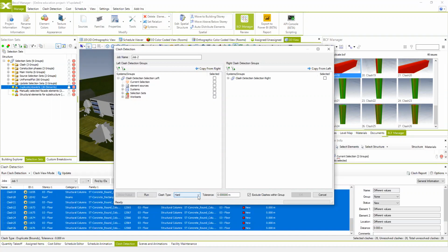Otherwise, if you want to check your BIM model elements just for some kind of touching, and if your BIM model elements go parallel between each other and just touch each other, you can use something more conservative for the clash detection analysis, and that's the hard conservative type, which will identify not just the clashes and interferences caused between elements positioned at some specific angle, but even the elements which are parallel to each other and just touching faces.